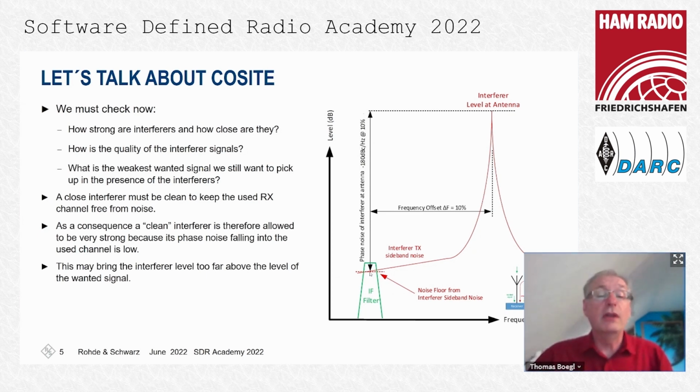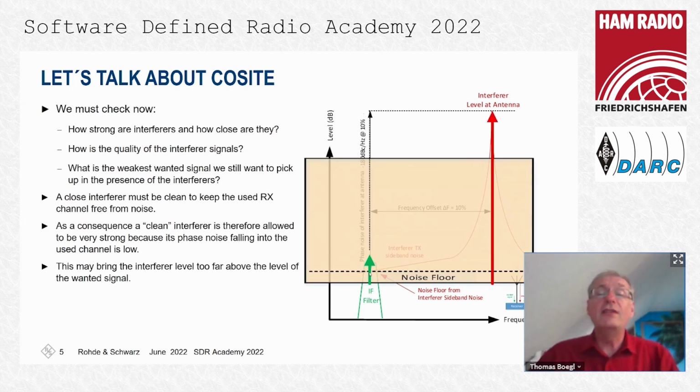And what we have to do now is bring all this into what I call the operating window of an A to D converter. So let's imagine this is a direct sampling receiver, and it wants to sample the complete spectrum from the HF band up to 30 megs. Then the operating window of the A to D converter, which is a frequency range and a level range, is just shown with this colored window. This can be pointed to the spectrum at the antenna level.